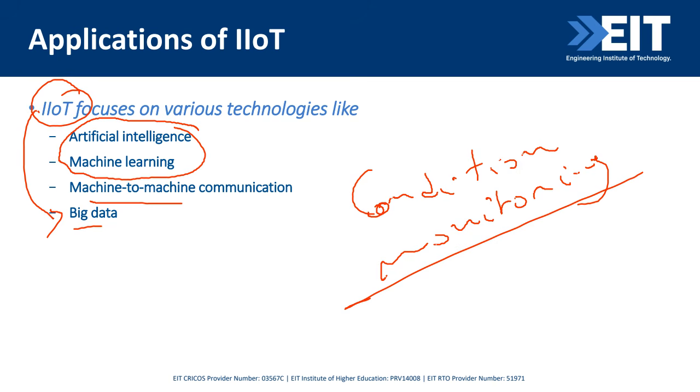Now, if they do the maintenance too frequently, it's also costly because you are shutting down in order to do the maintenance. If they don't do it frequently enough, the machine can fail without us knowing it. Again, it is costly. Ideally, you repair something when you believe there's a problem without it being a complete failure. Okay, now condition monitoring will allow us to do just that.